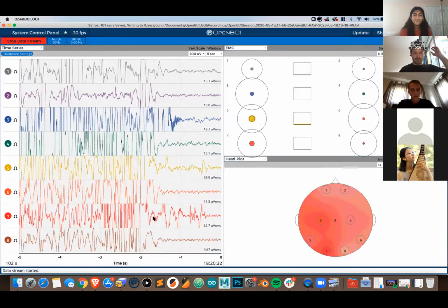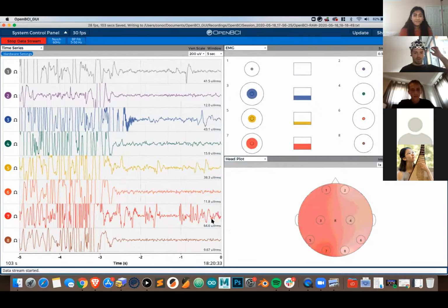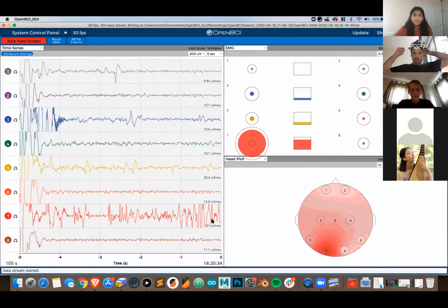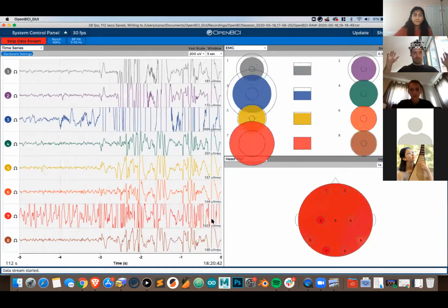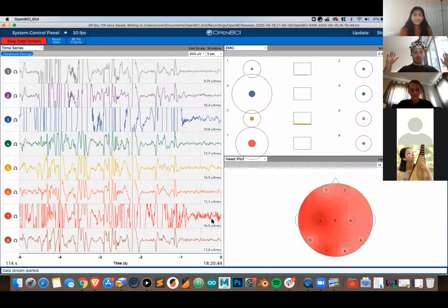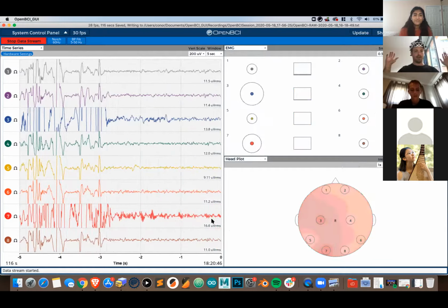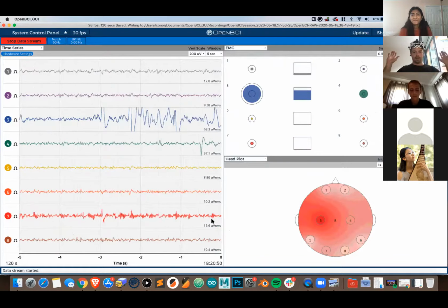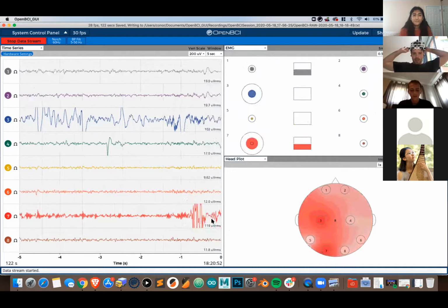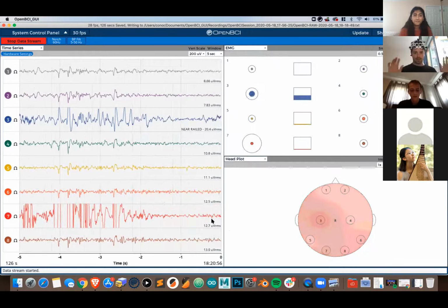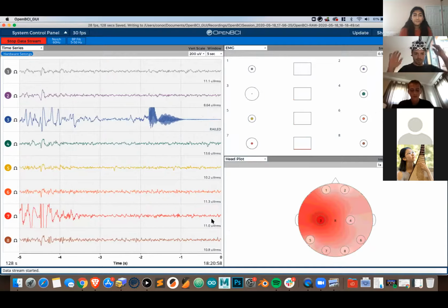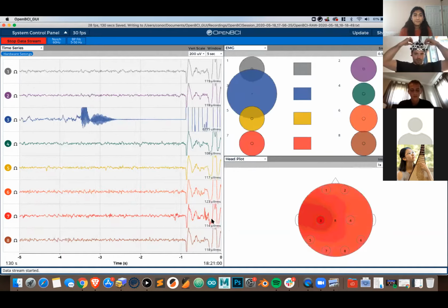All right, channel 7 is a little scratchy. It's jumpier than we want it to be. So I'm going to pop channel 7 in a little bit more too. And I know from years of experience where these are located, but it wouldn't take you that long to figure it out if you had your own headset. Cool. All right, so it's not the best it could be, but it's pretty good data, actually. You can see that there isn't too much scratchiness. Now channel 3 is freaking out, so I'm gonna try and pop that in.